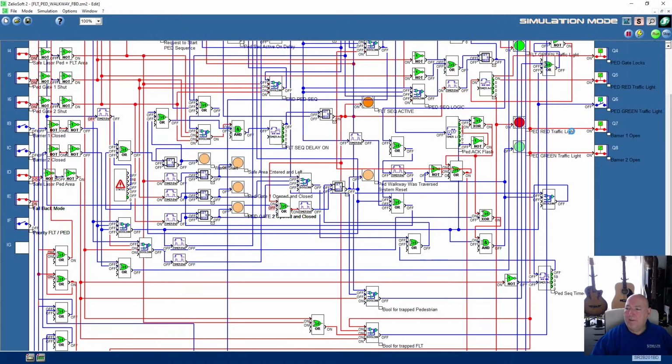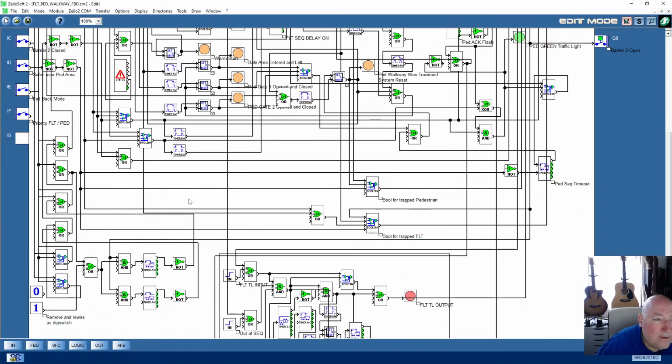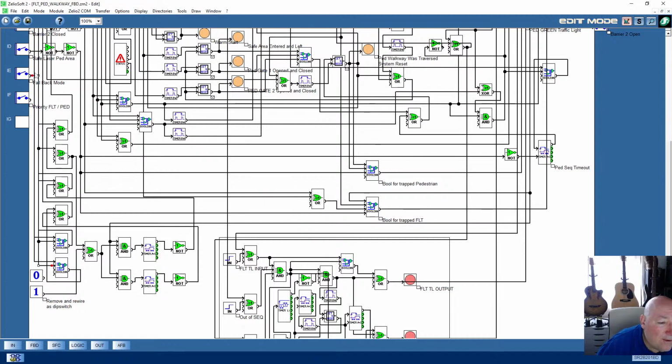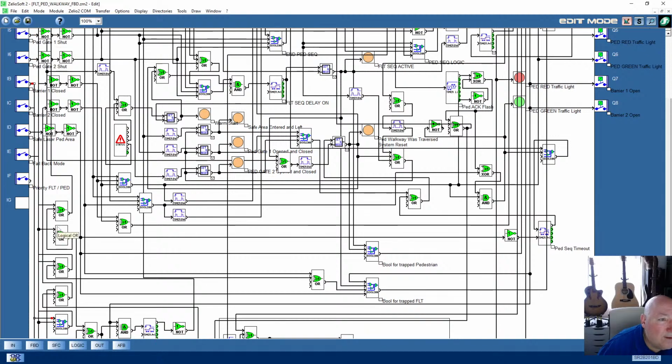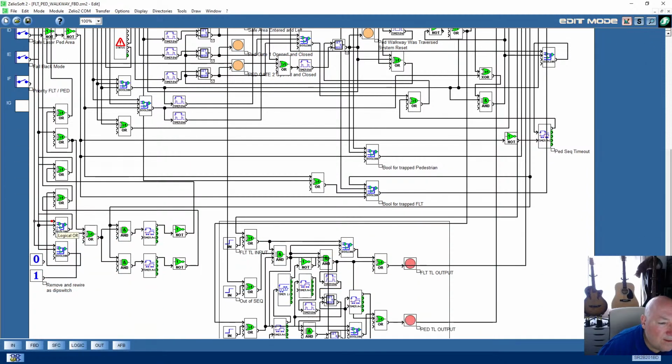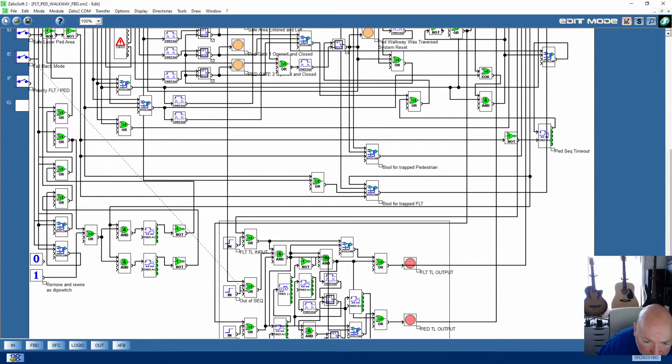Right, so let's stop it a minute. Let's find where our signals go here from our fallback mode. So it comes down here to there and to there, I think. Yeah, to them too, to the Boolean. Right, so the fallback mode, we need to know when it's switched on. Now this Boolean, what's it in with? The barrier one closed, right, it's cutting off them, isn't it? So we'll have to go to the source here, to the switch itself. And we need to come into the OR gate here, whenever that's on. So that should be easy enough to do. Just pull a cable from there to the spare input here.